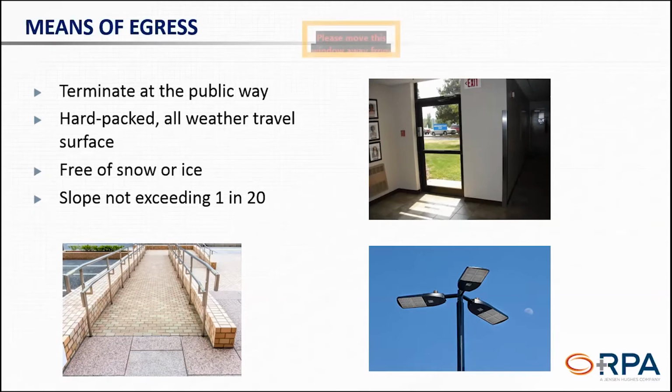So sometimes that's 2 light packs, sometimes that's 1 light pack with 2 bulbs in it. We've seen the LED light packs. Is that 1 bulb? Is that 50 bulbs? Well, typically it's how many control boards you have in that light pack. That's usually the key to tell us if that's enough lighting that the failure of any one control board won't leave the whole light turned off. So you have to do some homework on that with those LED light packs, but it certainly is something to consider when you're changing out your fixtures.